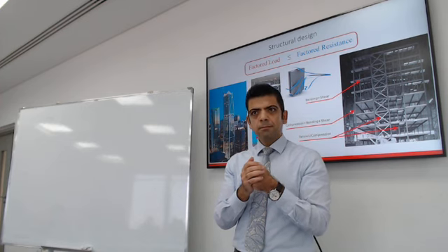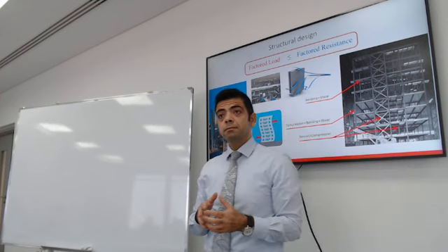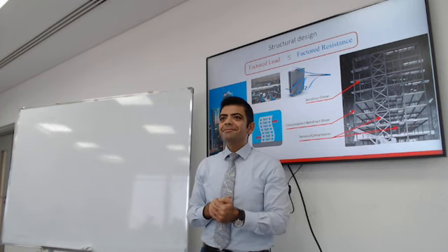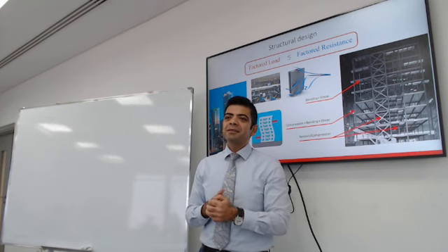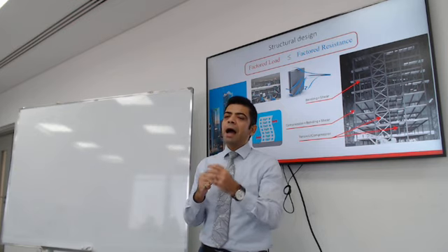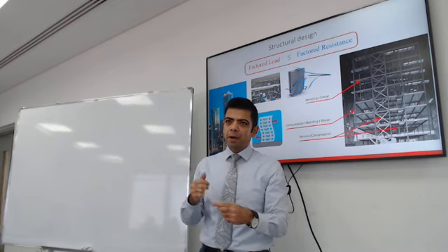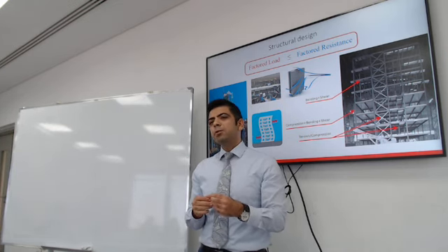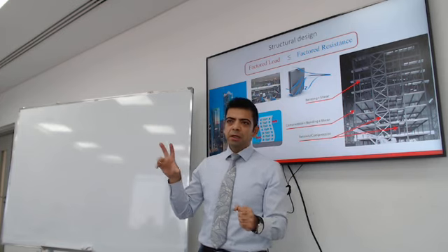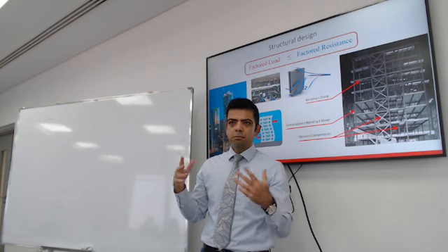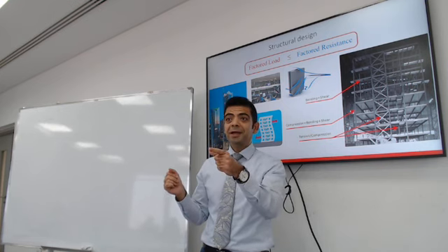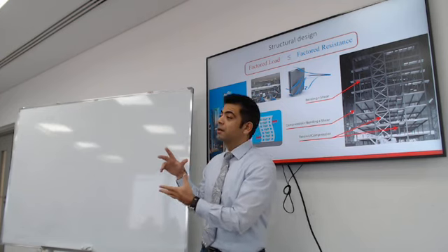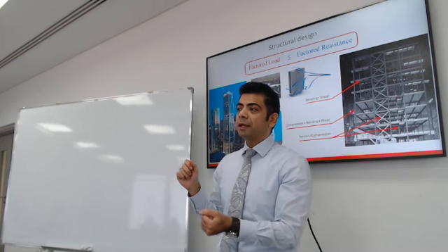If you're going with a manufacturer and you want them to produce it for you, if they're already pre-produced, you have to see the table sections, what they offer, and then see the closest one according to the moment of inertia, according to the loads, the weight. Yes, I love it. So how are these tables calculated? Do you know how these tables are calculated? Which tables are you referring to? The dimensions or how strong the section is? Both. Okay. So how do you figure out the strength of the material or the capacity of the section? How strong the section can support the weight or the load on it?